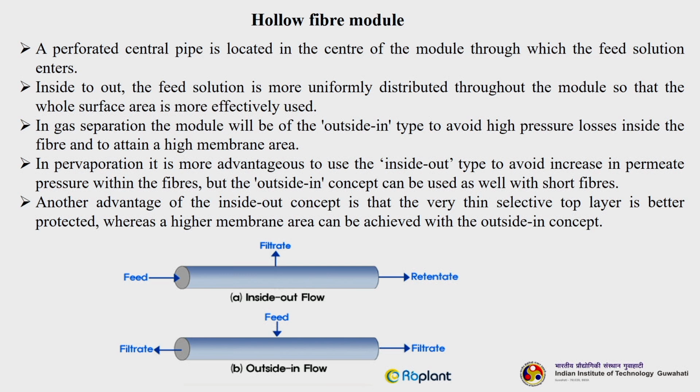And in gas separation, the module will always be outside in. Why? Because it is done to avoid the high pressure drop across the membrane, and to achieve a higher membrane area.